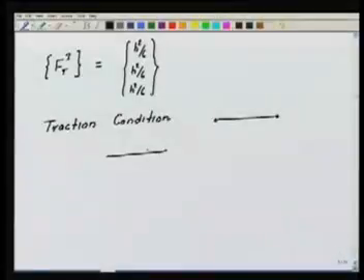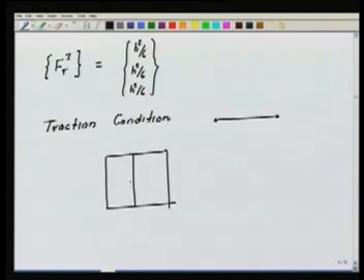That's why we will do them not at the end of our element calculations, but while we are doing the element calculations. So this is one major difference from the 1D case: we do not wait till the end of the whole assembly process and then apply the boundary conditions, but rather we do it while we are doing our element calculations. So how are we going to do this? Let's take again our domain that we have. Let me also make the mesh along with it.